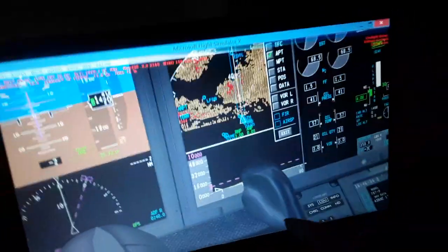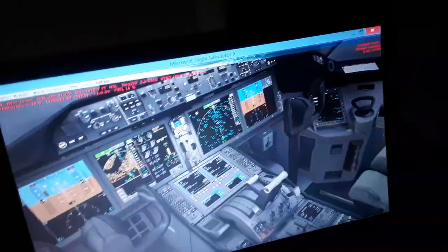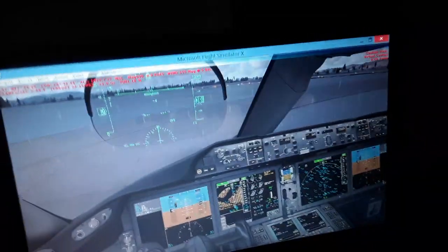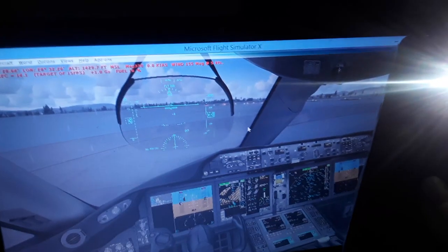When we fly, in the navigation display we can see how far above the ground we're going to be flying. You can see the mountains around us when we fly. So you will see many interesting things before we go into flight. Also in the primary flight display, we have the display of the LSZH localizer, the horizontal localizer, and the vertical glide slope from the instrument landing system. The LSZH localizer we use for takeoff and for landing. We have runway 14 and the Zurich International Airport in Switzerland.